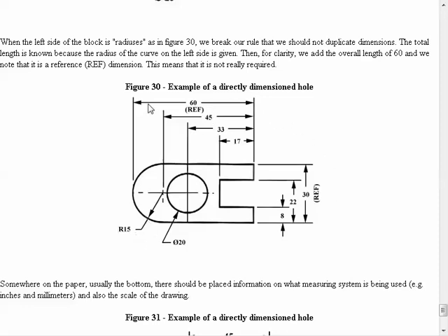When you put too many dimensions on a part, there is the potential for inconsistency. So if we know we're placing a redundant dimension on a part, we put the word reference for that dimension, saying this is not the primary thing that sizes the part, something else does. If all the dimensions are nominal, this would end up being a 60.